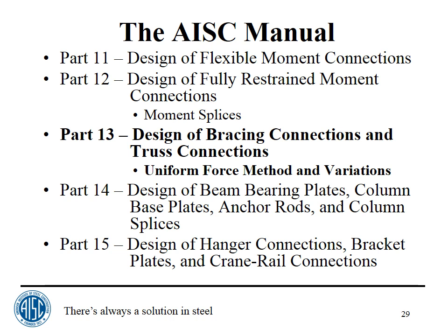And Part 13, which is sort of the meat of this particular night school, design of bracing connections and truss connections. The uniform force method, there are 3 variations given in there. There's the full-blown uniform force method, and then special cases 1, 2, and 3 that we will discuss not tonight, or this afternoon, but the next time, the second seminar.